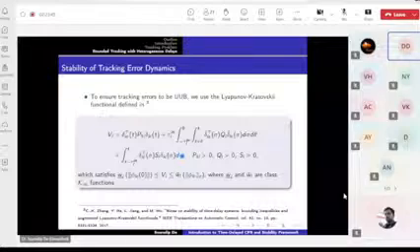But what is the guarantee that the feasibility of that matrix will be satisfied? That's how conservatism will come in your system. So it is a wise choice to make the LMIs of smaller size, and mostly we can get a feasible solution. There is no guarantee, though. Based on the system's architecture, these LMIs will have different kinds of delay margin in your system.